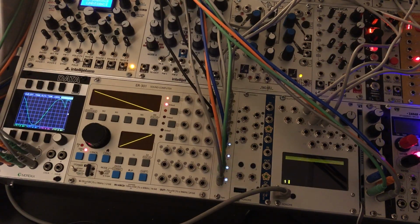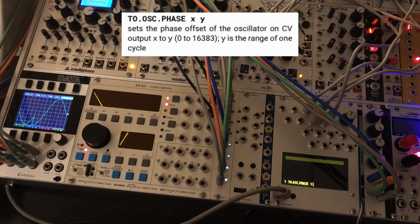So if I come back to script 1. Let's take the first oscillator and do TO.OSC.PHASE for number 1, and we'll just set that to 0. For the second oscillator, we'll set its phase to 4095.